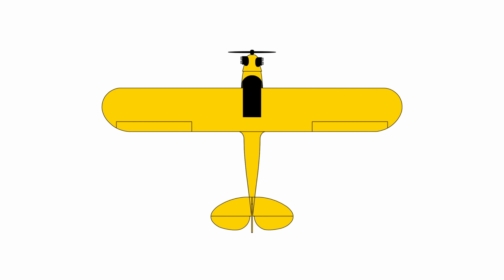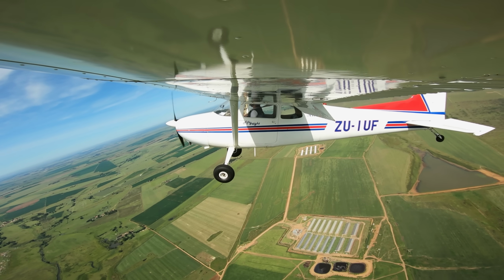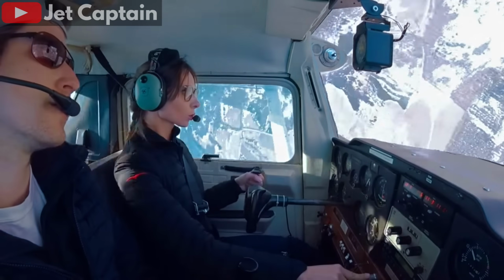Pushing too much rudder causes a skid, and we know how dangerous that can be, especially in the circuit. So, can the rudder stall an airplane? Indirectly, yes, but just like bank angle, it requires an increase in angle of attack. It's not that a skidding turn is inherently more prone to stalling than a slipping turn. The real danger is that a skid can easily result in an instant spin, and inadvertent spins in the circuit are almost always fatal, and that's why skidding turns should be avoided entirely.